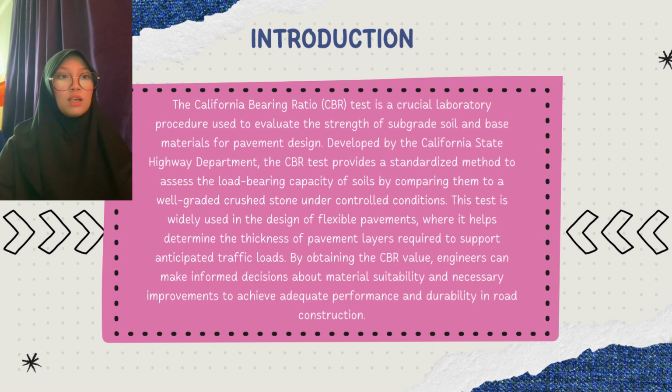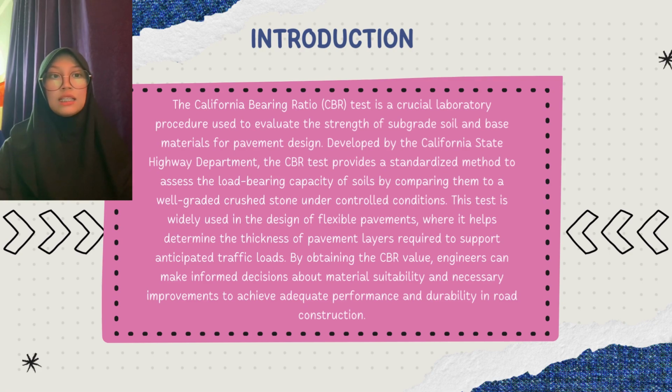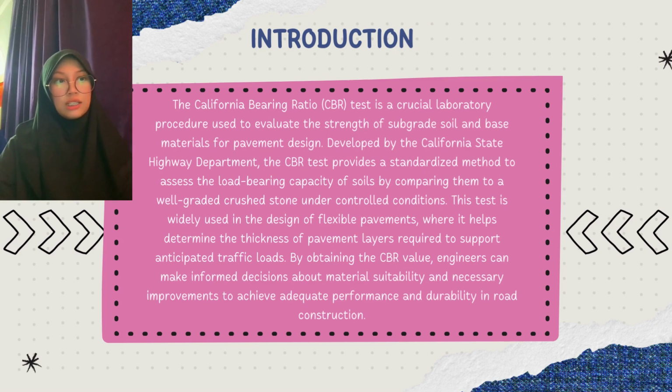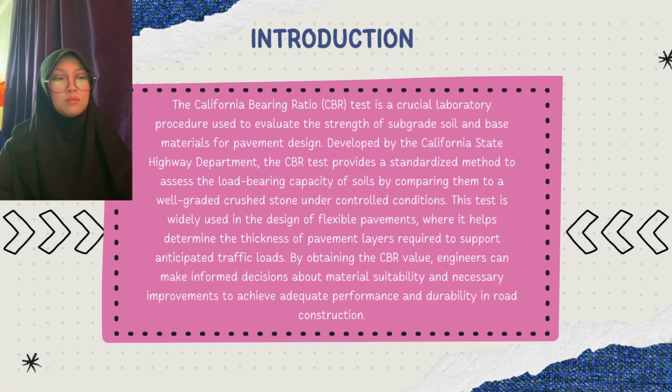This test is widely used in the design of flexible pavement, where it helps determine the thickness of pavement layers required to support anticipated traffic loads. By obtaining the CBR value, engineers can make informed decisions about material suitability and necessary improvements to achieve adequate performance and durability in road construction.